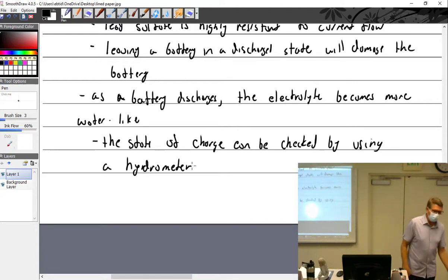And then, now that you get rid of all the acid, all you got to do is, and you got to be careful, you drop it, and that knocks off all the lead sulfate that goes down here. Then you take it upside down, you shake it, and you get all that lead sulfate out of the holes. And you can buy some new acid and then fill it up and then charge it.